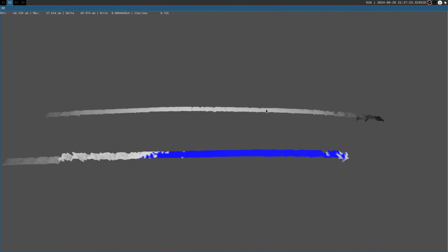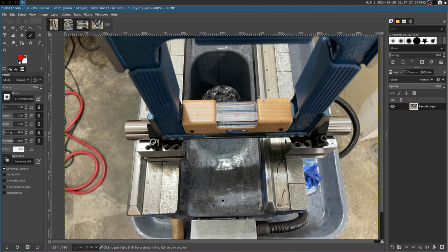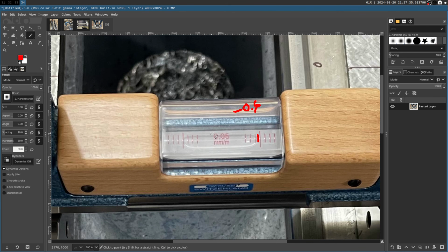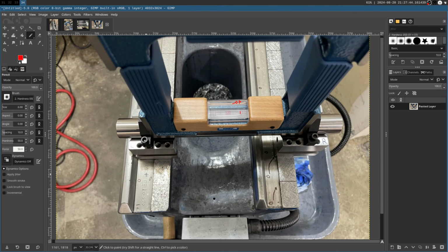Then, that's it. That now tells me what's going on. So, in this case, let's say this is a negative 0.5. Negative 0.5 in this case is half of this. So it is 25 micron per meter is what the angle is, right? That is a slope. That is an angle reading. It's not reading anything else.